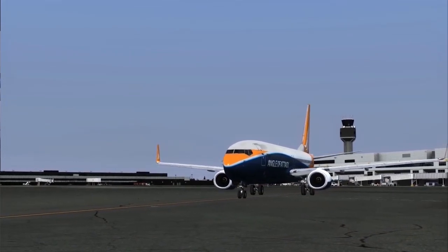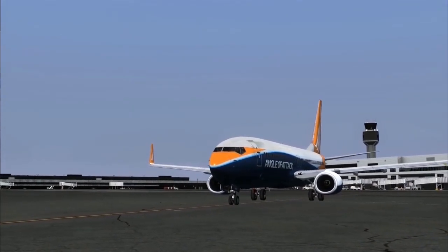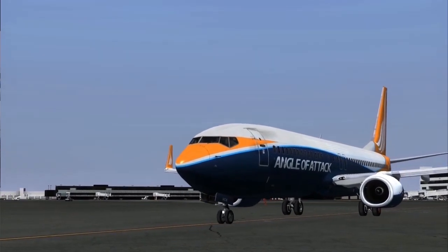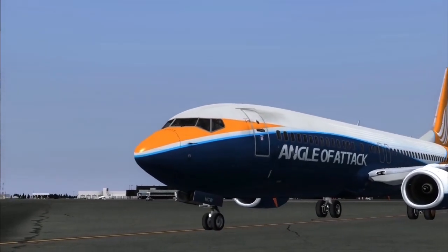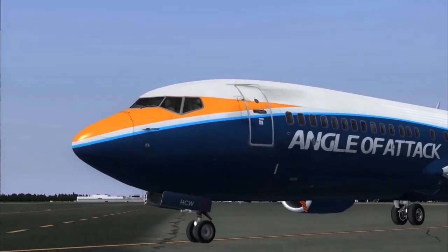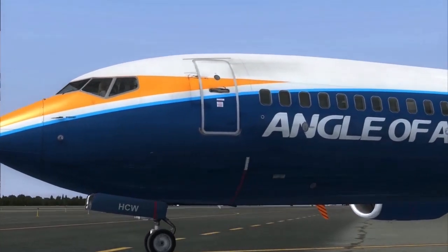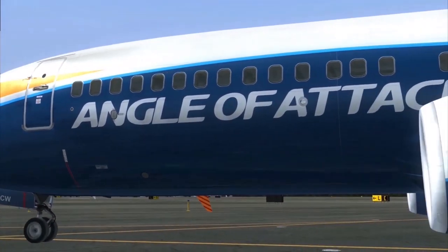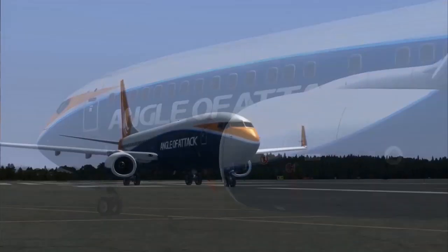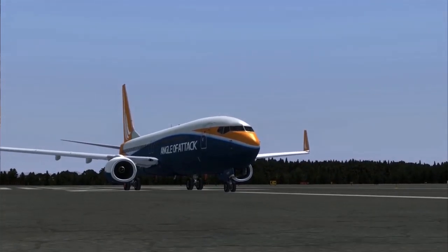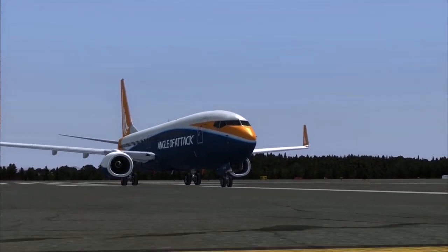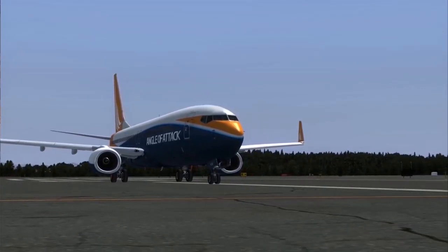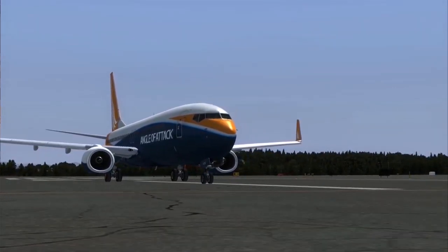The system senses the ground condition when the air-ground system senses compression in both main landing gears, engine N1 is lesser than 50% for 1.5 seconds or more, engine N2 is lesser than 84% for 1.5 seconds or more, or when both engines have been shut down. Engine parameters are extensively discussed in the 737 NG engines lesson.